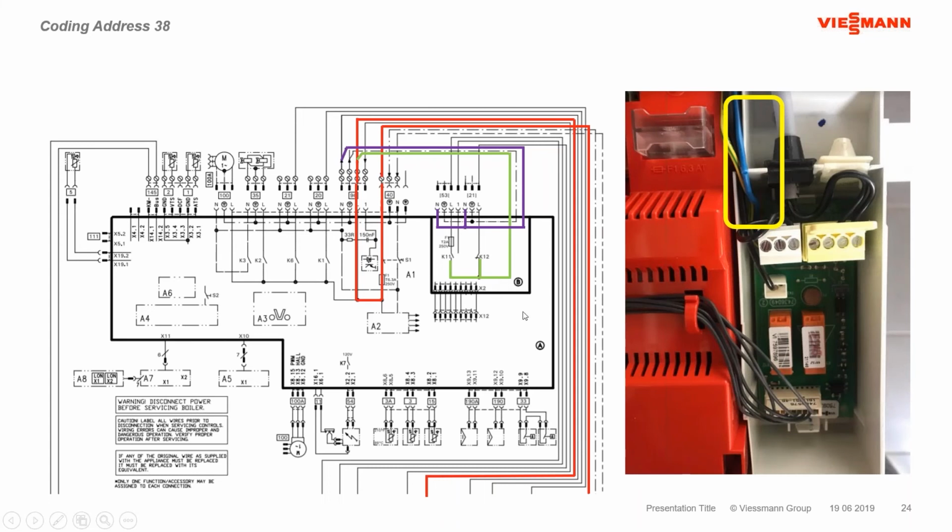So if we explode that up a bit, that's a circuit board here on the right-hand side that we're looking at, identified in this wiring schematic here with the 53 and the 21 plugs connected to it. That's the neutral outlined in the yellow box there. That little purple cable here is the blue neutral that you see actually in the picture here. And the line voltage, green here, is this little black plug with the white insulated connector plugged into that circuit board. So power comes in, and this power is sitting, waiting for these two relays to close.